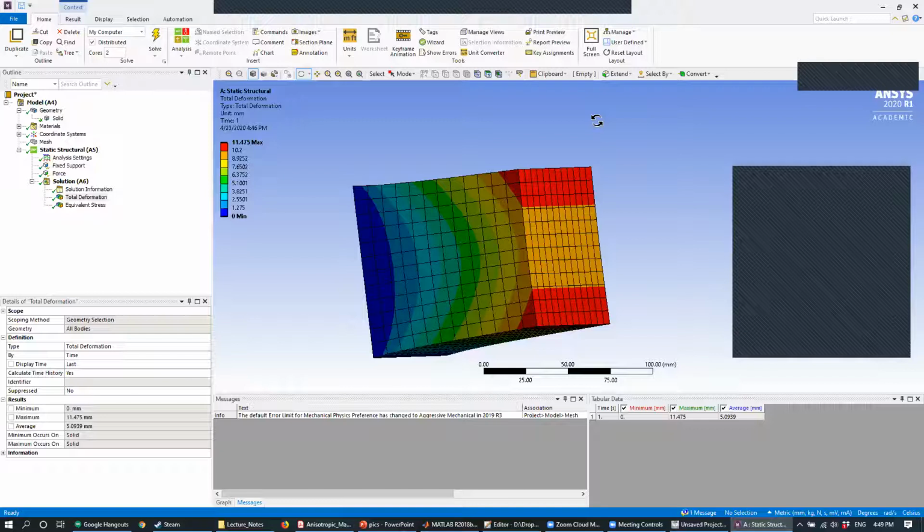Right. So the question is, can the shell be applied here as well? Yeah, absolutely. You can definitely apply shells and beams to these kinds of structures too. The shells and beams will take that anisotropy into account. The equations for that are going to be pretty complicated because you're taking a 3D understanding of a material property and transforming that to a 2D surface. So there's definitely some math going on under the hood, but I imagine Ansys can handle that pretty well.